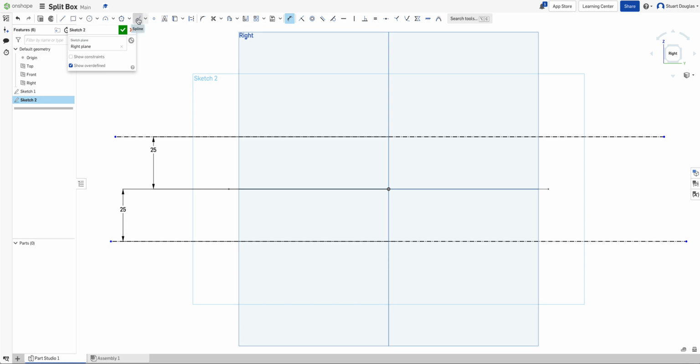We're going to use the spline tool. Now remember that this here is the start point and this here is the end point. I'm going to do my sketch here now, my curve sketch, and what I'm going to do on the top and bottom, I want the sketch to be outside, in other words, in this area and this area, outside of these points. So the surface is bigger than the line, okay? So I'm going to start off with the bottom one actually in this case. So the bottom one is going to be quite subtle.